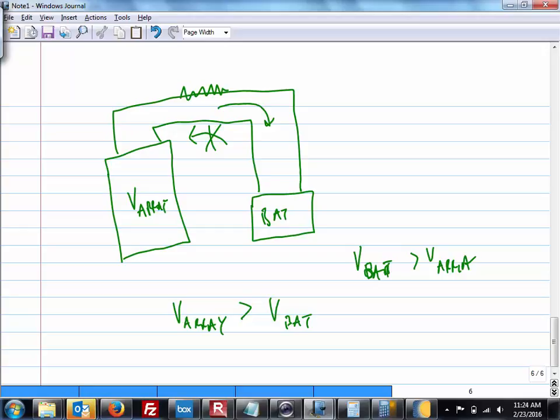Now the bypass diode, let's read that one. A bypass diode is a diode used to pass current around rather than through a group of PV cells that are shaded. There we go. In contrast to blocking diodes, bypass diodes are installed in parallel with modules or groups of cells. Each module may include 1 to 3 bypass diodes.